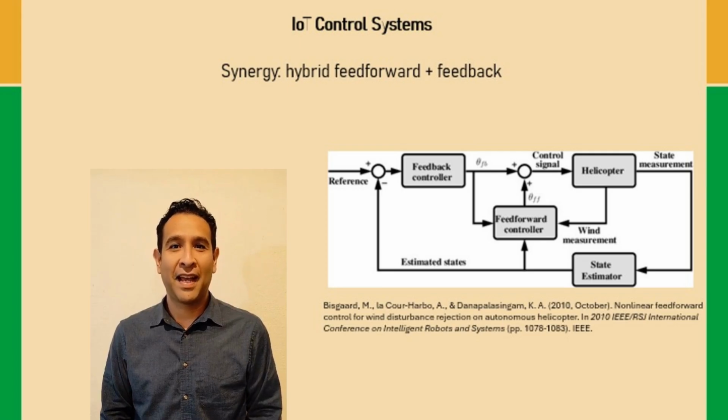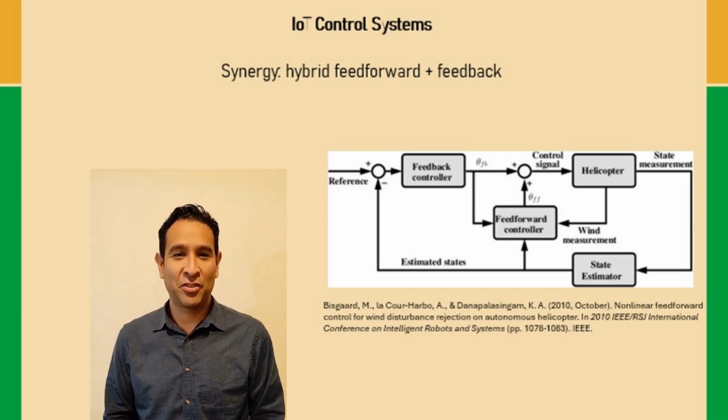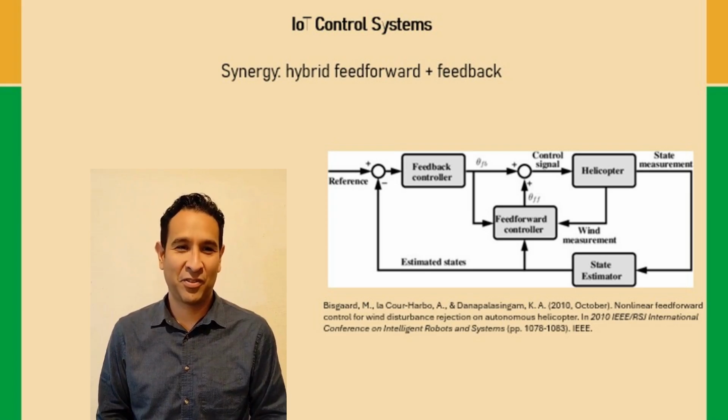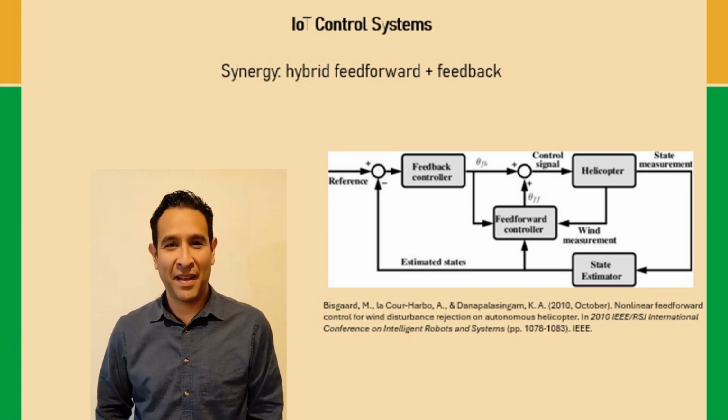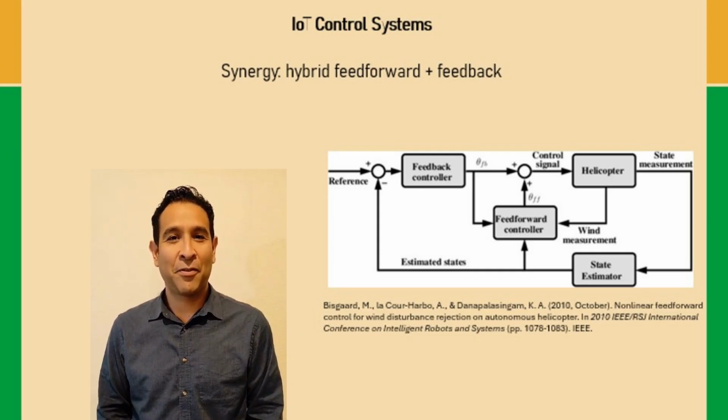The strongest designs combine both. Feed-forward knocks down the predictable part of the disturbance so the feedback loop can run gentler gains, focus on residual errors, and ensure stability. In practice, that means identify key disturbances, build a lightweight process model, add filtering to noisy signals, rate limit actuator commands, and keep anti-windup in the feedback loop. The result is faster response and solid robustness.